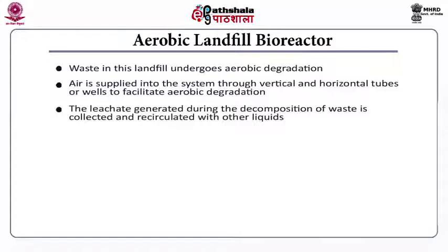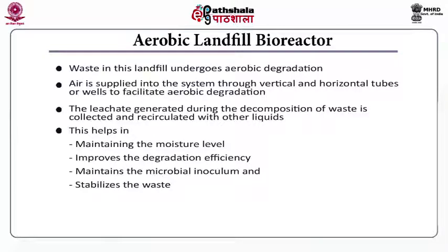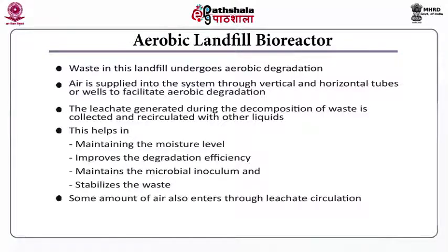The leachate that is generated during decomposition will be collected and recirculated with other liquids. This generally helps in maintaining the moisture level and thereby it will accelerate the degradation efficiency. Also, it will maintain the microbial inoculum within the waste mixture and it will stabilize the waste. Some amount of air also enters through leachate circulation, thereby accelerating the aerobic degradation.